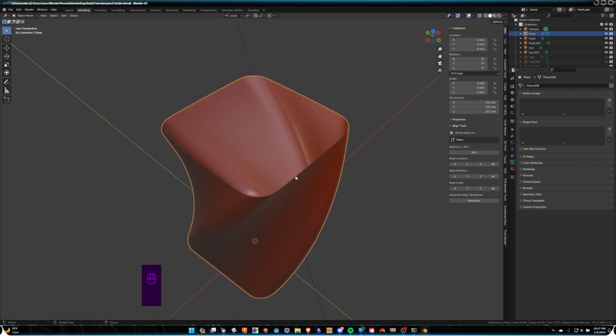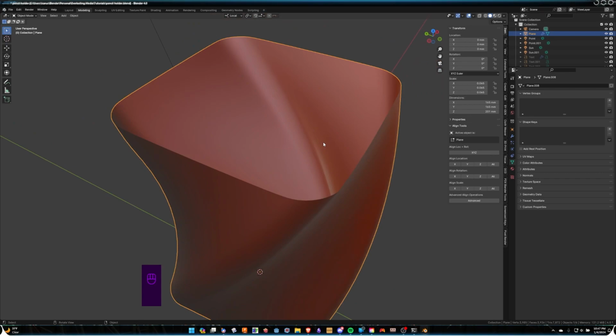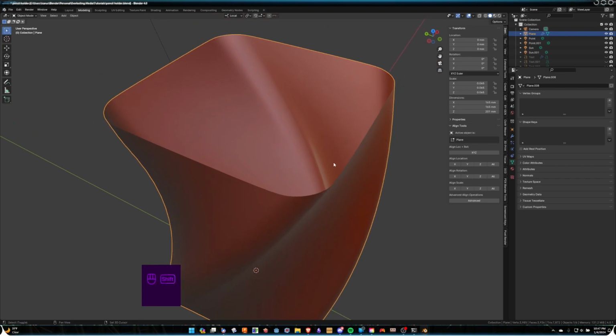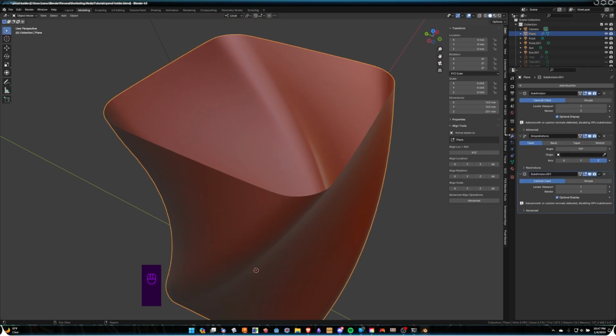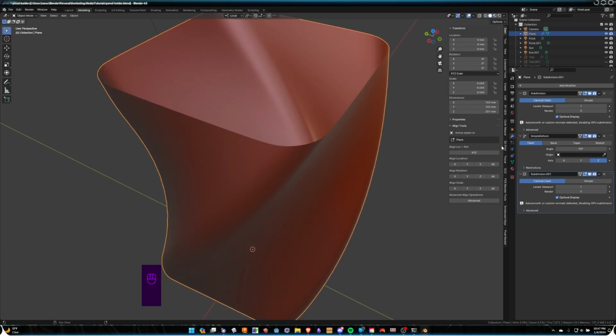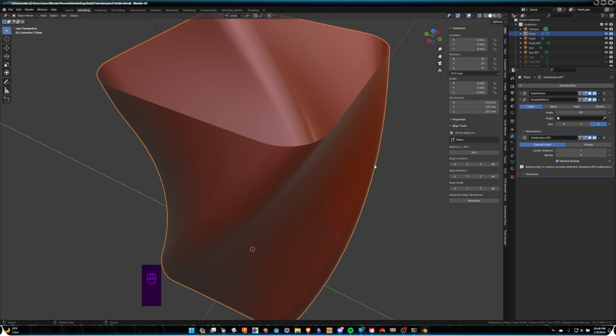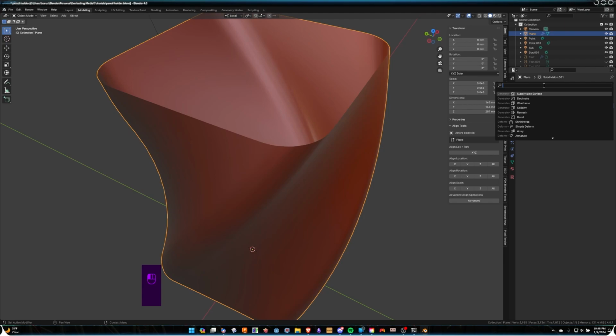Now, this doesn't have any substance to it, so if you tried to 3D print this, you probably wouldn't get very far. So the next step that we're going to do is come over here into the modifier stack. Now, we have our subdivision. We can probably just turn that on to simple subdivision because we're going to be subdividing and smoothing in layer. Our simple deform can be left as is. This subdivision can be left as is. And now what we can do is add a wireframe.